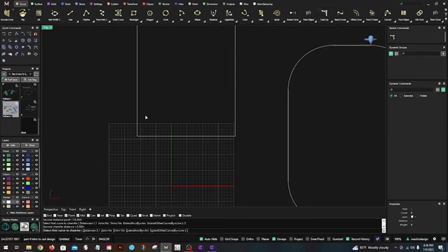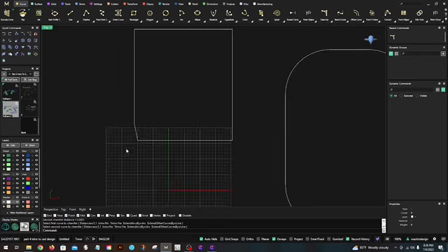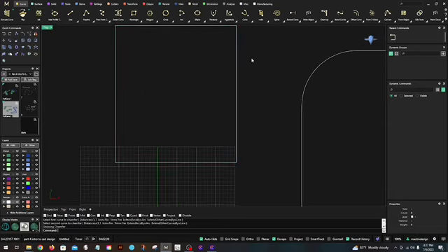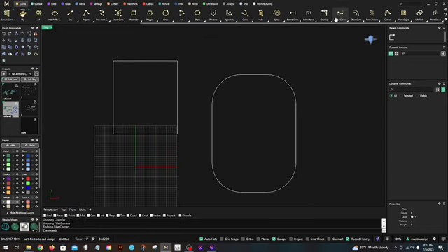Chamfer corners, first curve right here and here. Oh, okay, so in here in your command line, it says distances 5, 1. So it went up 5 and over 1, and I'm not sure why, but certainly that is not the default. All right, let's see. Chamfer corners, select first curve to chamfer. The distance is 5, 1. Do you want us to trim? It says yes.